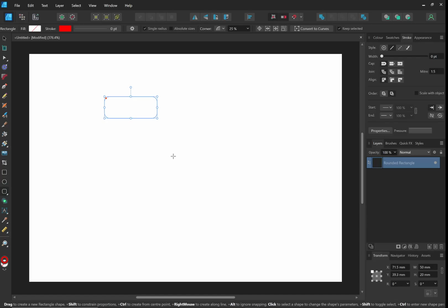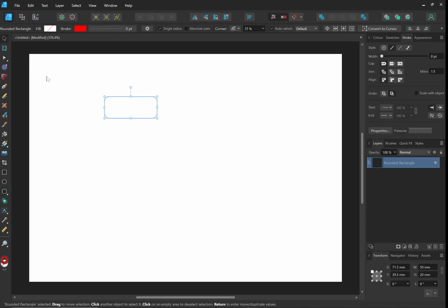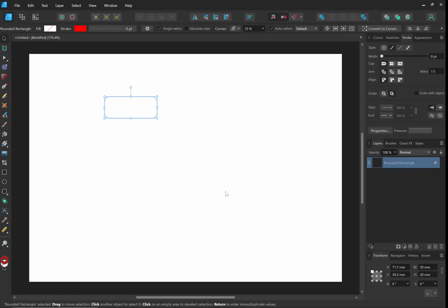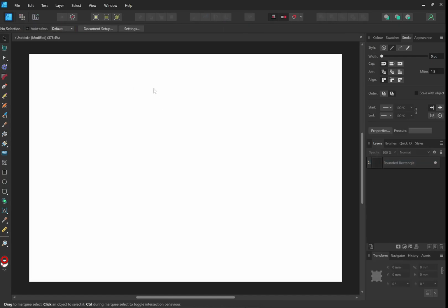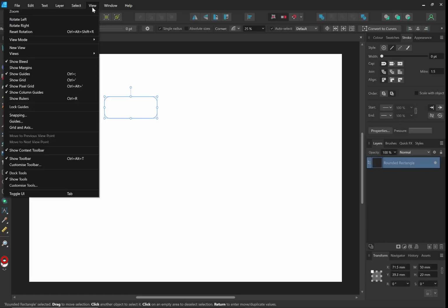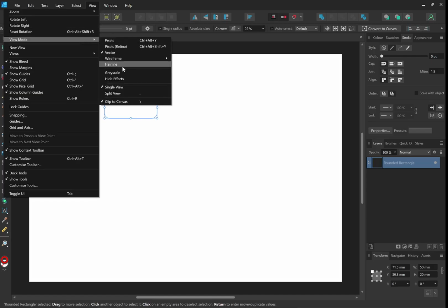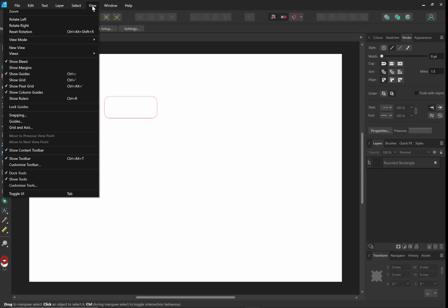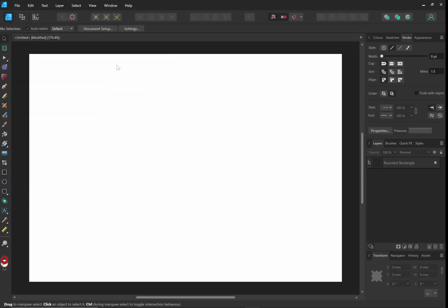That's just the shape here. And I think if I press somewhere, oh, well, it's there, but it's disappeared. Let's highlight over it. So it does exist. It's just not showing up because I think it's so thin that it can't be seen. Now, there's a way that we can view this. View, is it hairline? Okay, so we can actually view this. If we go to view and we change our view mode to hairline, it's going to show us, because right now it's too small, it doesn't exist.